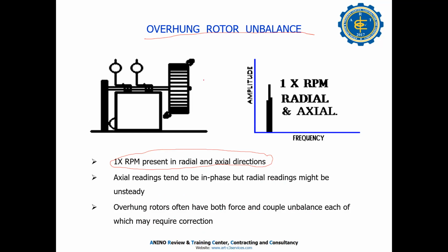So if you have unbalance, you have overhang, normally there is high 1X. What we did in our overhang, we only monitor. For example, when we run this overhang motor, vibration is high. Normally, we get 5 mm to 6 mm or 7 mm per second. That is high. But we accepted. What we did is only monitor for a couple of months.